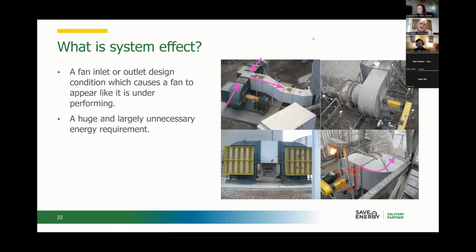If your system is underserved, you speed the fan up, you put a bigger fan in there, you do something, but it has to be accommodated in some way. Or in the case on the right, you say, okay, we're going to have to take that elbow off the discharge and put a long straight piece of duct in there. If we really have to turn it, we'll do that further away from the fan. That's a little bit about what system effect is all about. The bottom line is you want clean ducting coming up to the fan, and nice, clean, straight ducting leaving your fan.